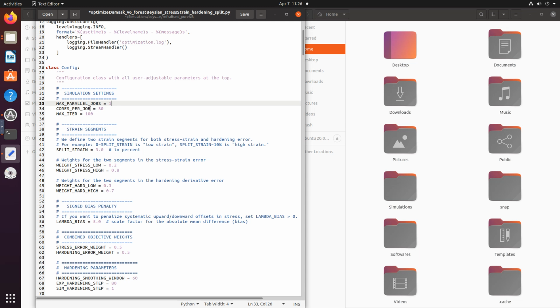If my geometry is 15 by 15 by 15, this number of cores per job has to be a whole number that the total of my pixels is equally divisible by. If you divide that by 30, you will get a fully resolved number. So this is fine. If I, for example, use 13, which is not a whole number divisor, the simulations, instead of getting faster, will become slower, because now it has to shift data every time and it is a mess.